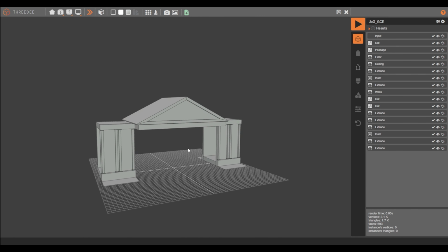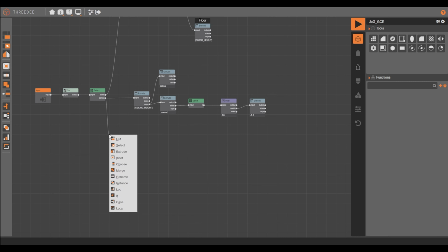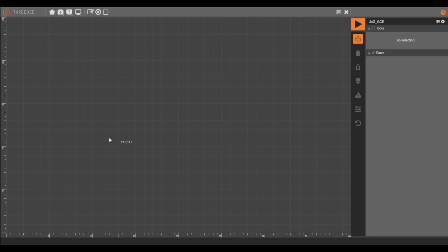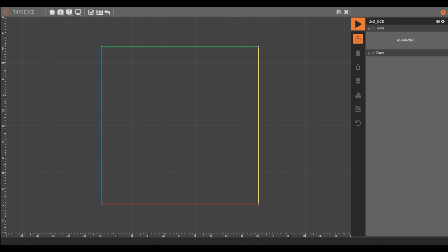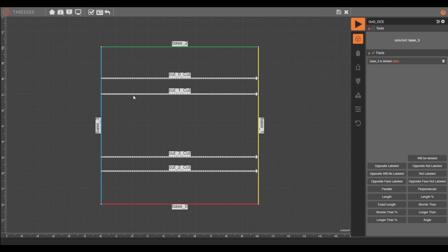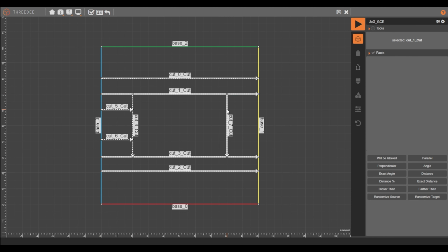Taking into consideration that one segment of the profile roof front was labeled as 1, we will create a select node from the sides of this extrude and select label 1. Then we will create an inset of 0.8 and finally an extrude by amount of -0.5, adding detail to the roof of this section.